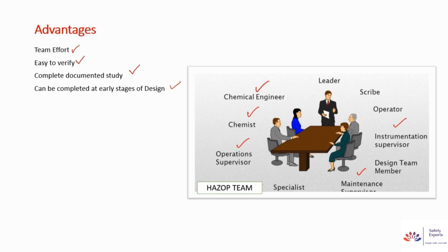It does not need the data sheet of the instrument. It does not need any quantitative data about the equipment or the process. So it can be completed at the very early stages of design, and that is very helpful, because when you give any recommendation at the early stages of design, the chances of incorporation increase, because the cost is less at that time.